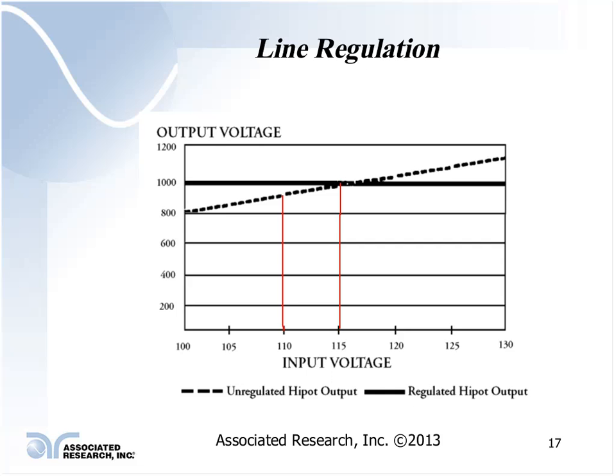So what happens if you had an audit during this time and they came in and they said, well, we want to witness your test. And now they look at the Hipot tester and the standard says you should be testing at 1,000 volts, but you're only testing at 900, you may have a problem, okay?